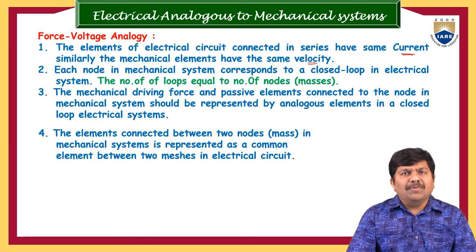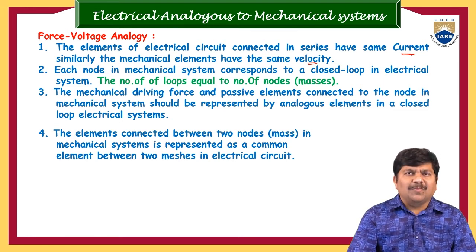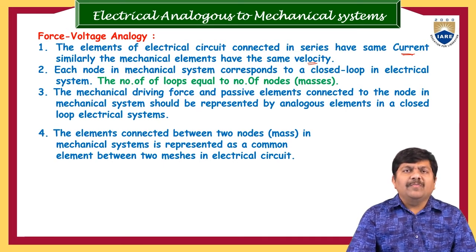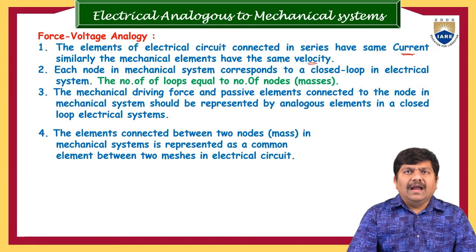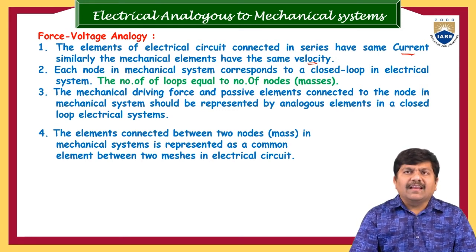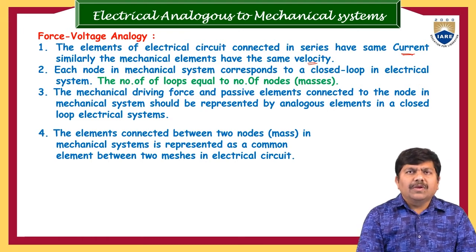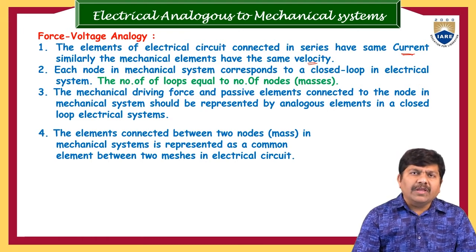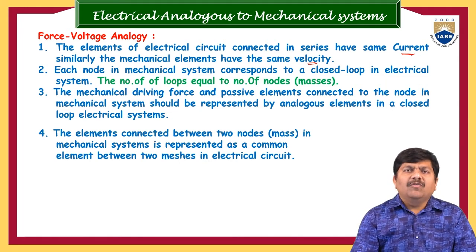So in order to simplify electromechanical systems with the help of electrical technology or electrical principles, it is necessary to derive the electrical analysis parameters of the mechanical systems. And the last point is, the element connected between two nodes in a mechanical system is represented as a common element between two meshes in electrical circuits. Just keep this point in mind, and while we are talking about the problems, we will recollect this point and elaborate on the exact sense of this particular statement.